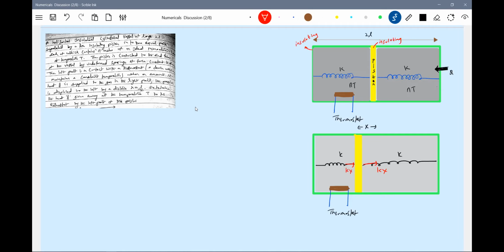Then the pressure here, what can the pressure be? Will it be the same or different? No, the pressures will be different. So the pressure is PA, and this will be P dash A. Now equilibrium has been reached. Now the temperature of the gas, let it be T plus delta T. This will remain as it is, T. Now the piston is in equilibrium. If you can draw this second diagram, you are in a better position. Now what is X given? L by 2. This much is there.